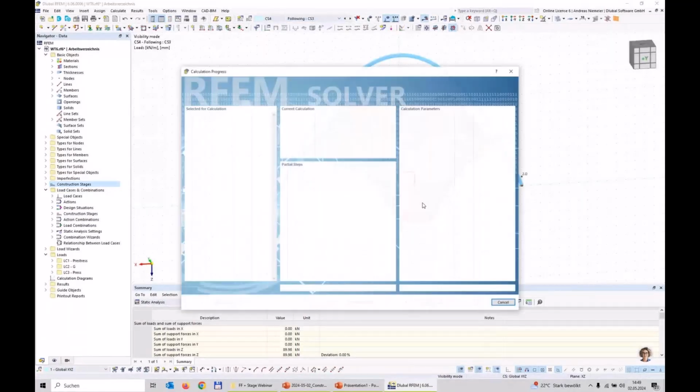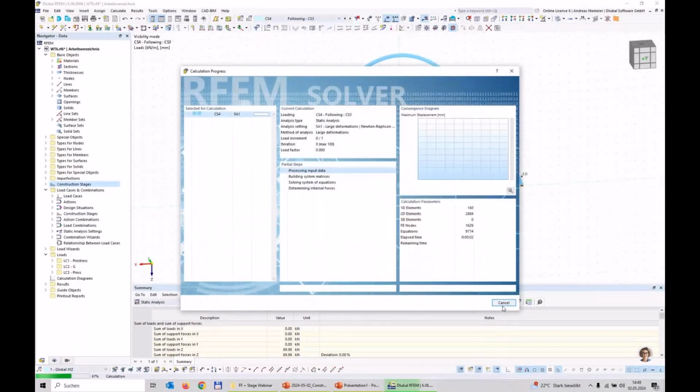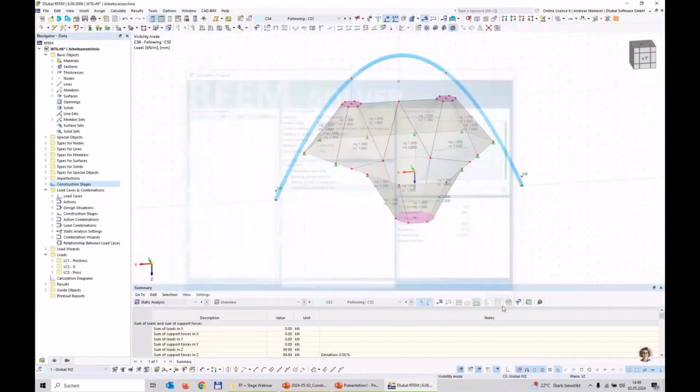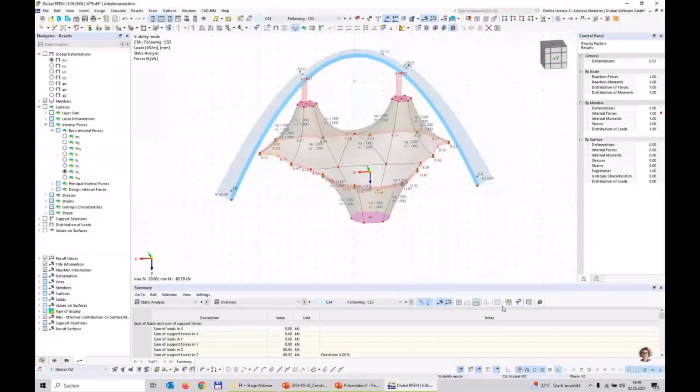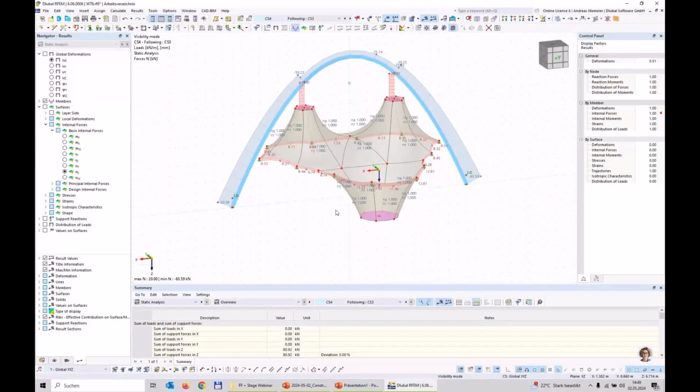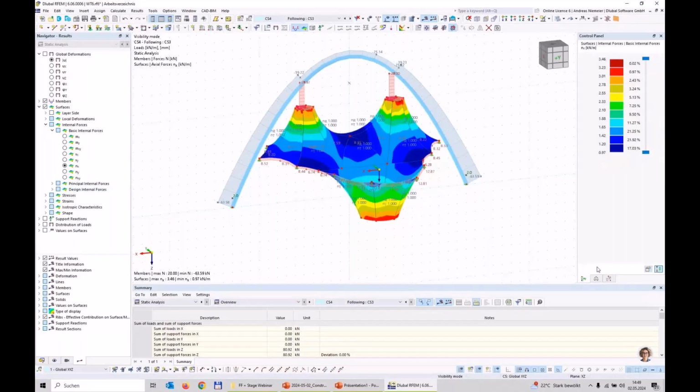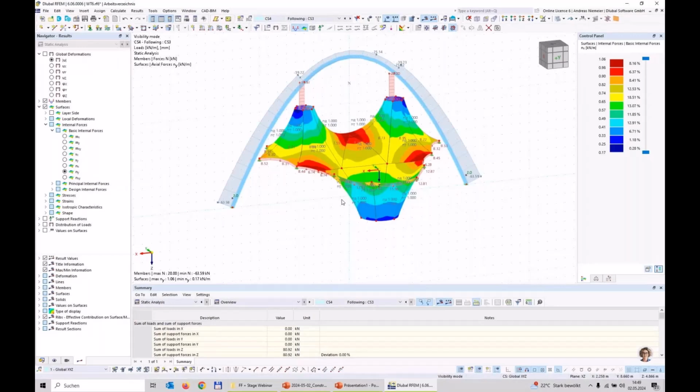And okay. And now when I calculate the CS4, you should get the result without the inner steel frame, and the arc on the outer side should take over everything. And you see now, okay, we have here this arc, we have here now the hangers, and the structure is supported and working. And now let's see results. So if we watch now results in membrane, you see, of course, the span direction has not changed really much, so it's still from 1 to 3.4, but the tangential direction is a little bit critical. So we are coming to small to 0, so 0.17 to 1.